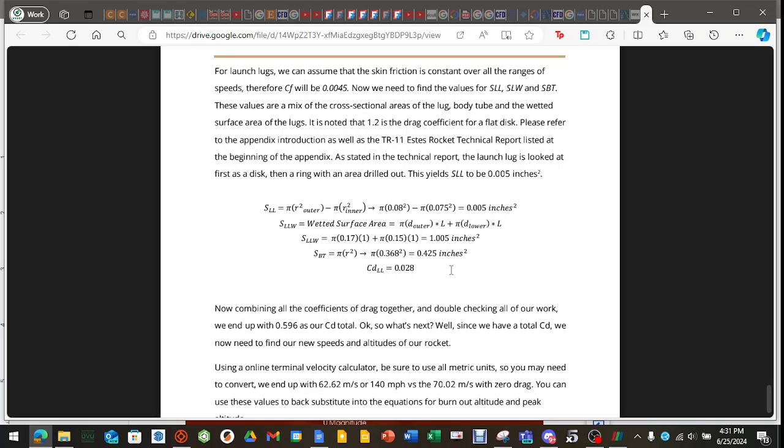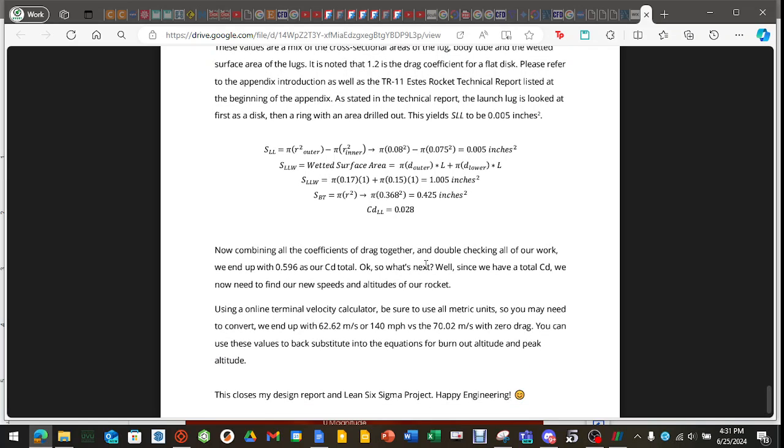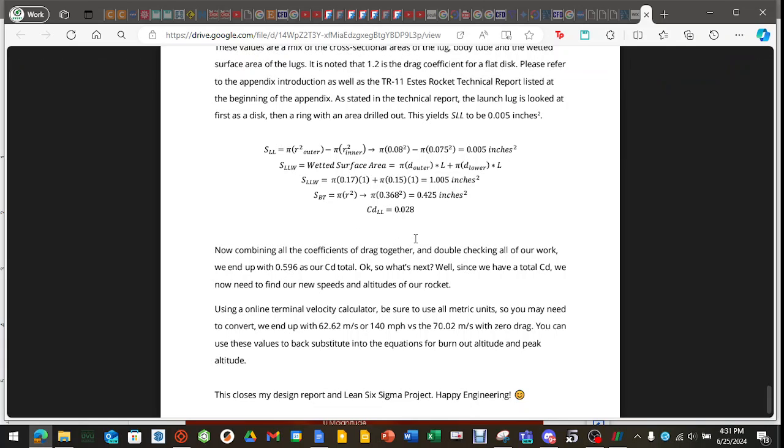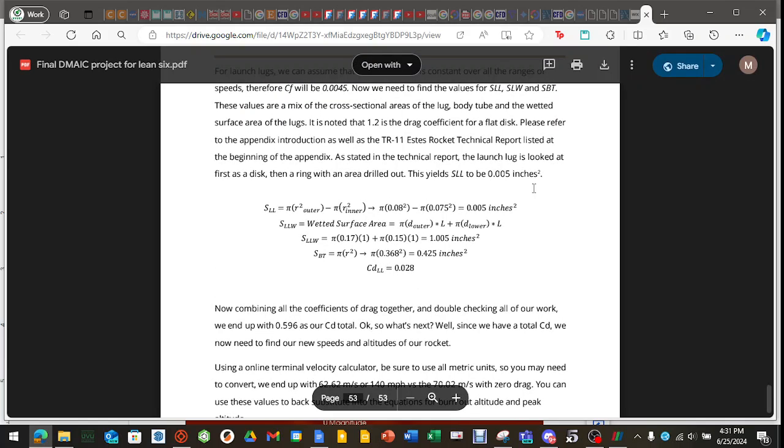And see what you come up with for hand calculations using the same velocity, because once you get all of your coefficients of drag, remember, things are going to change based on velocity. So once you start, like this is 0.6, notice we didn't use velocity whatsoever in the geometry equations.